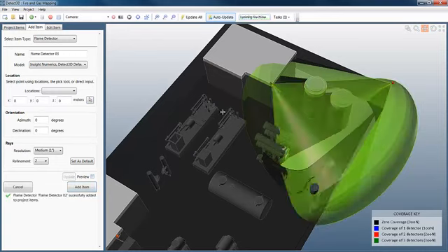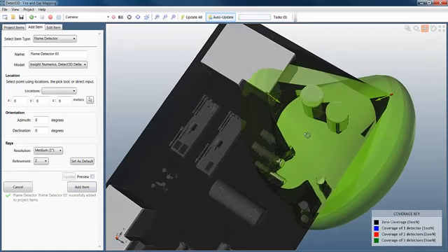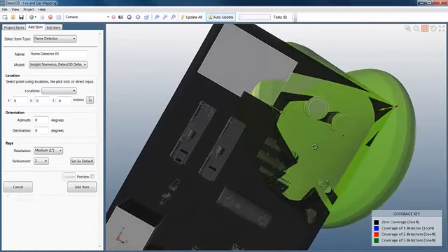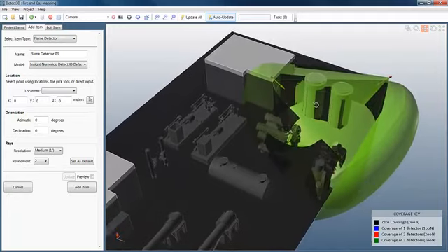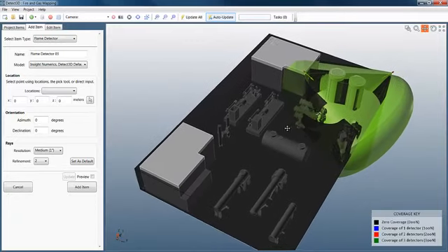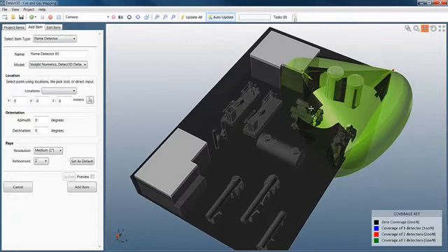This looks good, so I'll add it to the project, and notice that the new detector has been added and that the 0 visibility isovolume has been automatically updated. We can see immediately that the blind spot has been greatly reduced, so we're making progress, and I'm going to add some more flame detectors to the project.